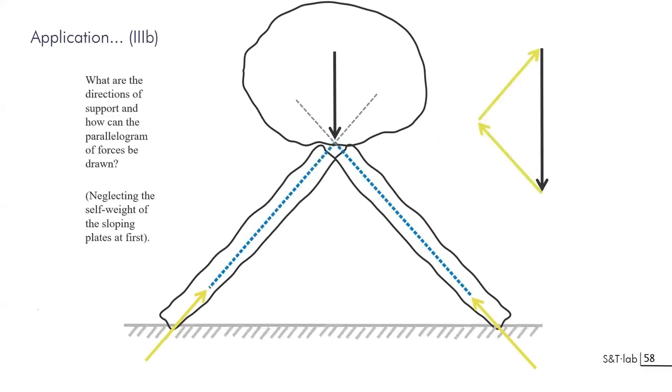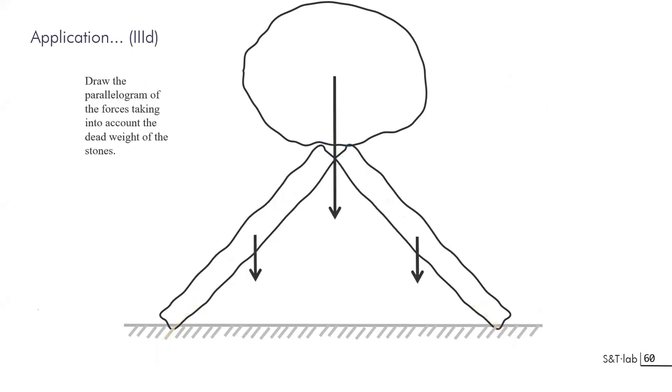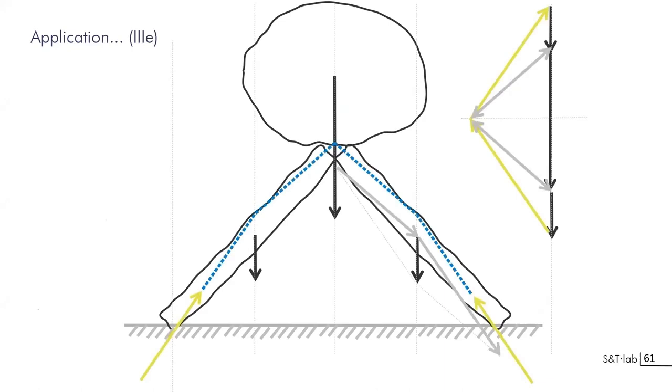and you can make the distribution as before through the points of contact here and here, building the first force polygon. Going ahead, if you are not going outside of the stone, you have to be more precise about the way things will be designed here, and you see the force polygon getting more and more complex. I can go ahead with this using the weight from the supporting stone and having the same kind of resolution.